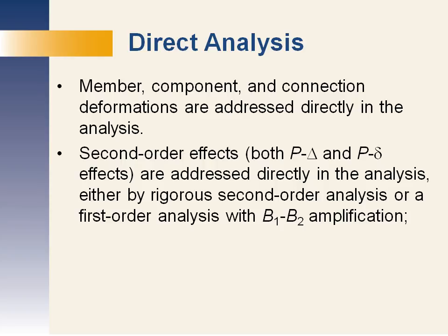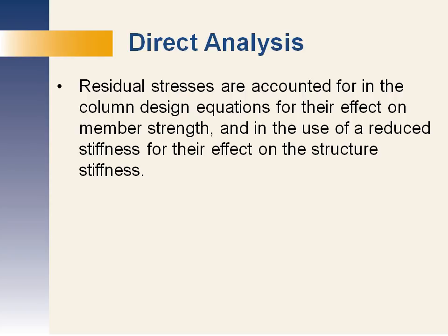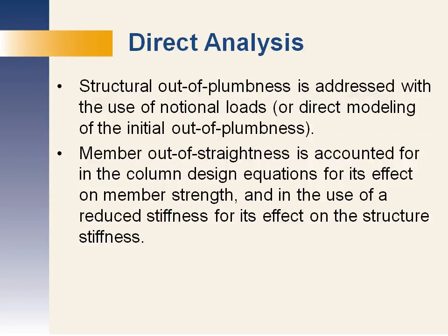Well, member, component, and connection deformations are addressed directly in the analysis. Second order effects, both P-delta and P-Delta and P-little-delta, are addressed directly in the analysis, either by doing a rigorous second order analysis or the first order analysis with a B1, B2 amplification to add the second order effects. Structural out-of-plumbness is addressed with the use of notional loads. Alternatively, you can do it with direct modeling of the out-of-plumb structure.